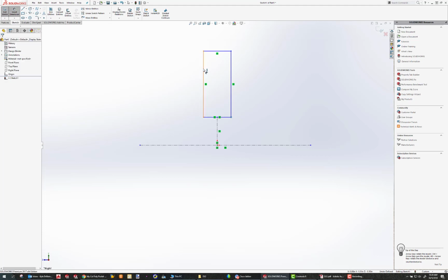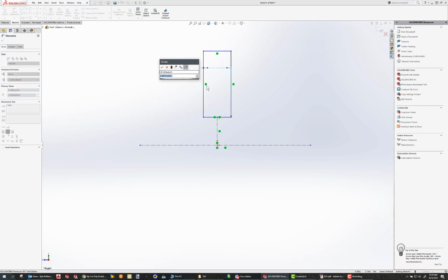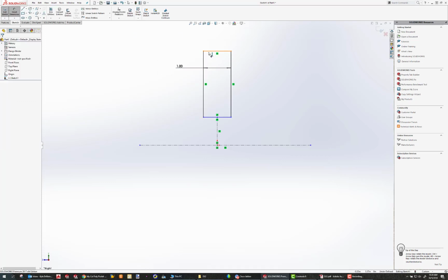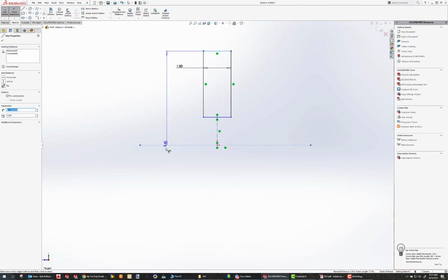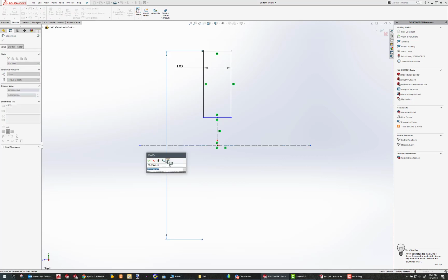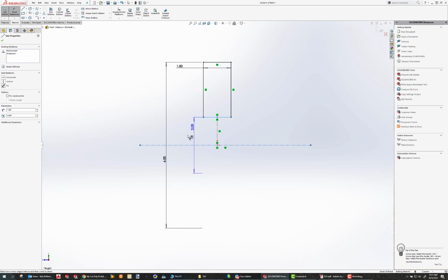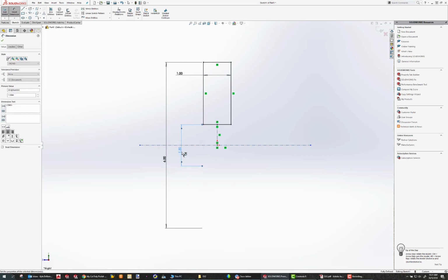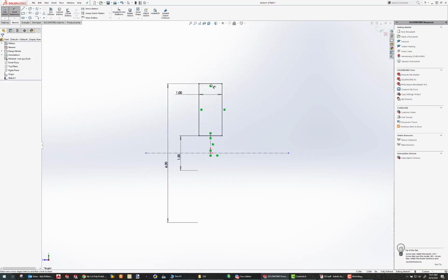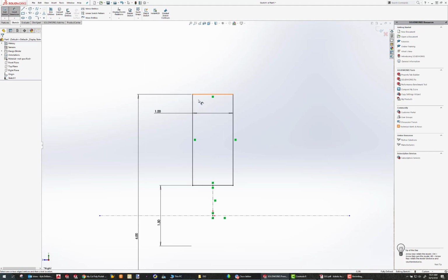The width of this is 1, and now let's select the diameter. The outside diameter of my part is 6 inches. Notice if I dimension from a solid line down to a center line, and if I drag my mouse below that center line, the dimension doubles. This is SolidWorks recognizing that you're attempting to create a revolve and you want to input a diameter. So my sketch is fully defined, but I want to build in that pulley race into the top here.